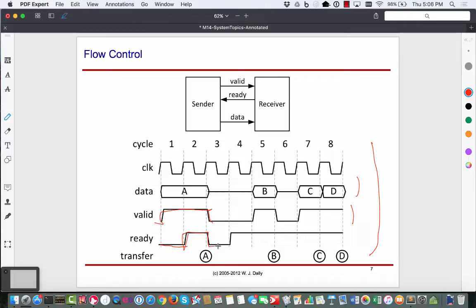There are many different ways this protocol can be structured, but essentially data exchange can take place when there is data and the receiver is ready. Both conditions have to be met, and through this bidirectional signaling, we make sure of that. And pretty much one has to do this because otherwise your design constraints become too rigid. That is, both sides have to operate at peak speed, so you cannot have cheaper devices and things like that. So this kind of handshaking is extremely common, and there are many ways of organizing it.